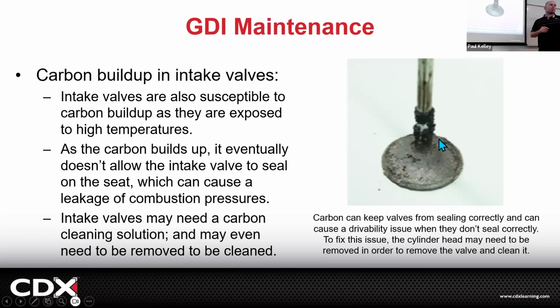The top tier fuel is going to be critical, but these may also need a top engine clean, or even walnut blasting. This is more maintenance for technicians. If it gets that much carbon, it'll actually misfire. Or if you put something in your fuel, it could hopefully help, maybe. I don't know. You know what I know works? Me cleaning them. They have GDI spray you can use to clean, and it'll soak on those, and then you'll start it up and a bunch of smoke will come out the tailpipe and you'll be like, oh, they're clean now.